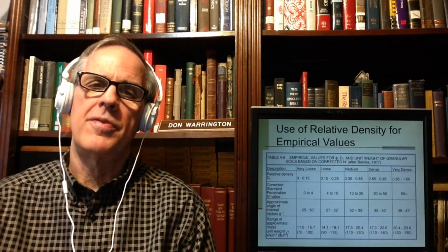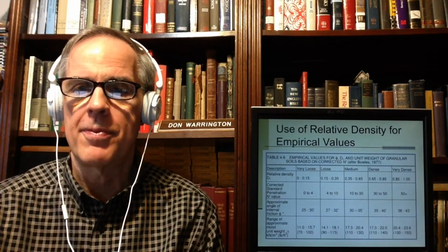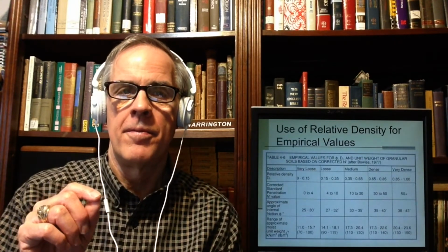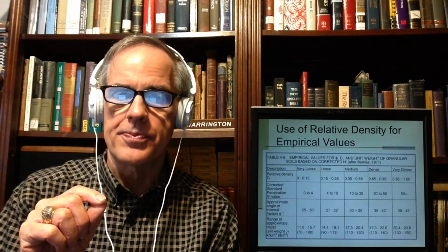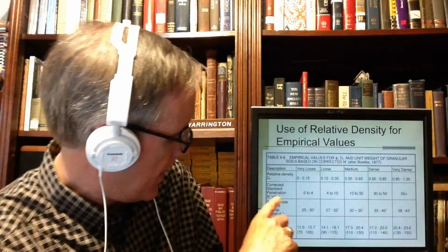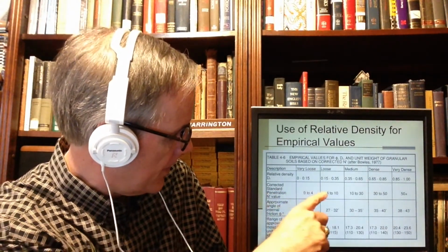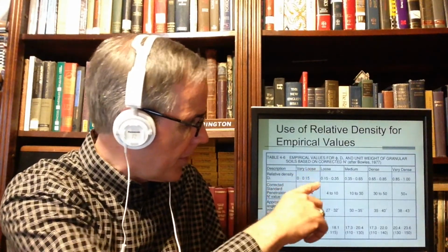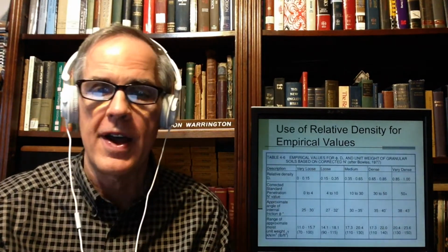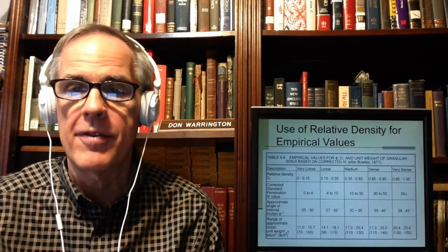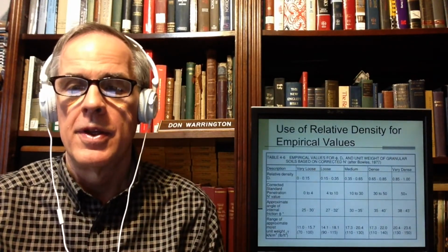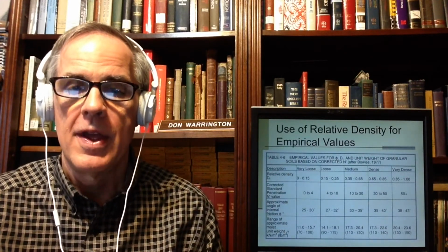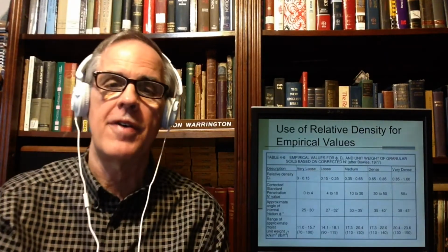Now, I said that relative density is mostly used with cohesionless soils, and this is an example of that. You will recall the last time I talked about the SPT test, we had N values and the corresponding descriptions, very loose and so on. We'd already looked at that. Very loose means relative densities from, say, 0 to 0.15, then loose 0.15 to 0.35, and then medium 0.35 to 0.65, and so on. If I say a soil is medium, it probably has a relative density of about 0.35 to 0.65, and we probably saw a corrected SPT value of 10 to 30.